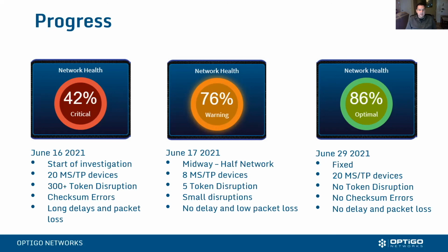And then another question here. You mentioned you use Siemens. Does it work on other vendors? JCI, Metasys, any others? Visual BACnet itself is vendor agnostic. So all we look at is BACnet data, and it doesn't matter which vendor it comes from. Whether it be Delta, Trend, Siemens, JCI, Honeywell, Schneider, and there's over 1,040 now, I believe, BACnet vendors that have BACnet vendor IDs, this software will work for all of them. We look at the application of how BACnet is being applied and look at the corrective measures in that respect.